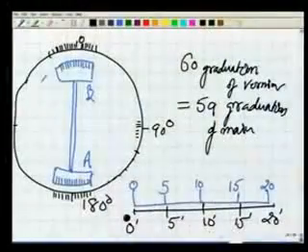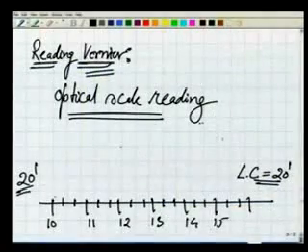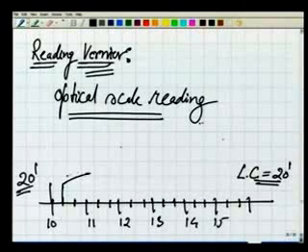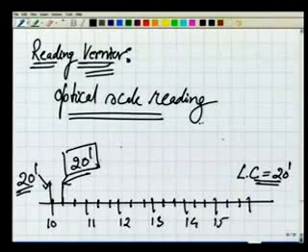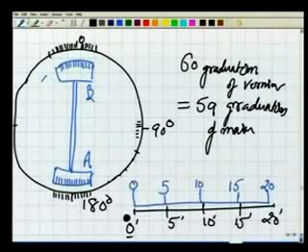But this is fitted with a vernier. As you can see here, in this case, A and B are verniers. How these verniers are actually there, and how we improve the precision using these verniers. Now this particular part, if you just look at any little graduation, this is for 20 minutes. I expand this 20 minutes and I am showing it to you here. So 0 and 20, this is 20 minutes.